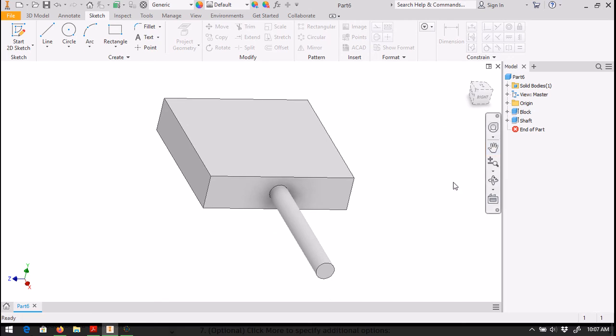Now, what if you want to zoom in? Let's say I wanted to zoom in on the circular feature here. There's several different things I can do. And by the way, there is another video on pan, zoom, and rotate as part of this YouTube channel. But additional zoom commands are found in this drop-down menu here. I can zoom window, zoom selected, or just plain zoom.